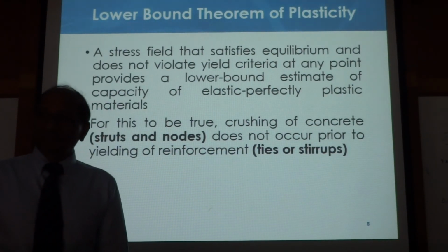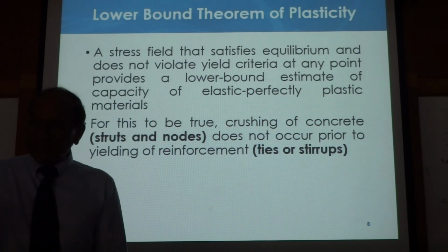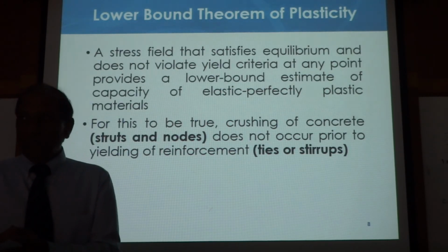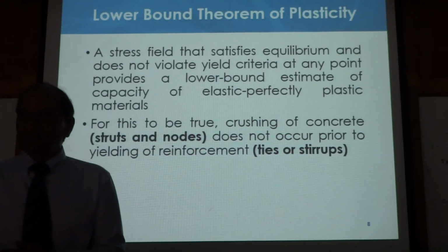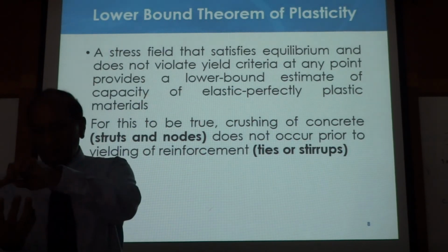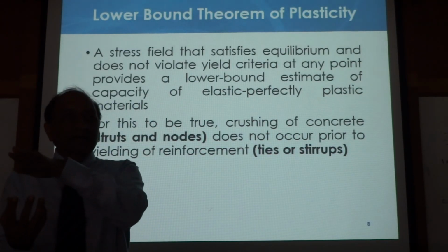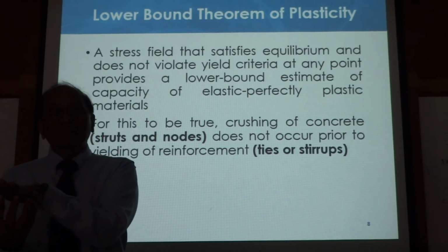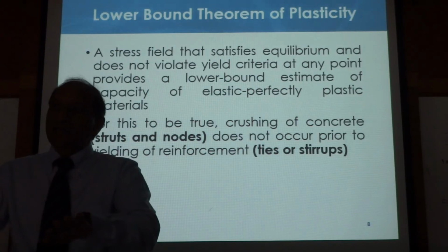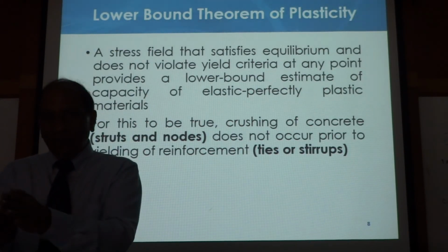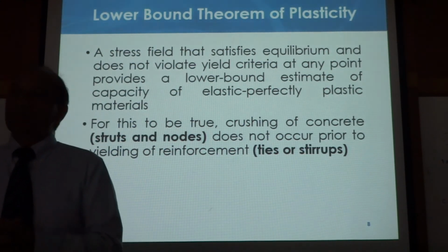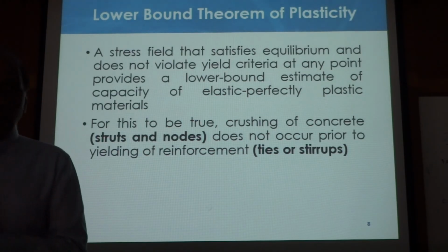Why did it stop? If the stress level of that area has already been exceeded and your foot has already crossed the limit of deformation, how come it stopped? It stopped because the area immediately under your foot was highly stressed. It became plastic, that means it started to flow, but the surrounding areas were not so heavily loaded. So after some large deformation, the load distributes to the sides, to the areas around that.